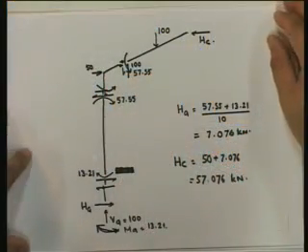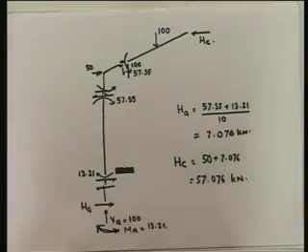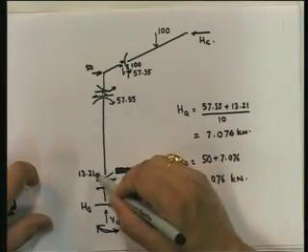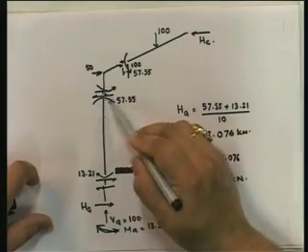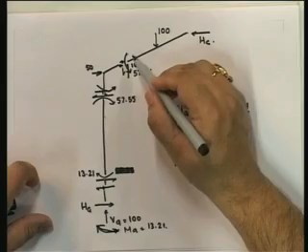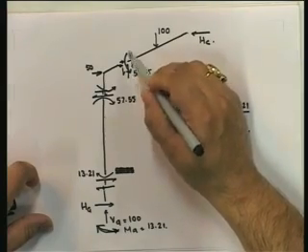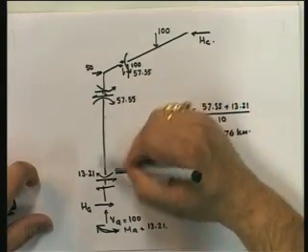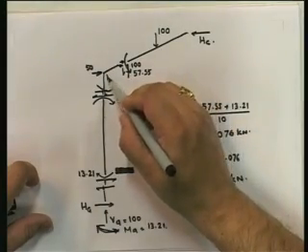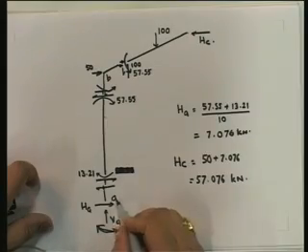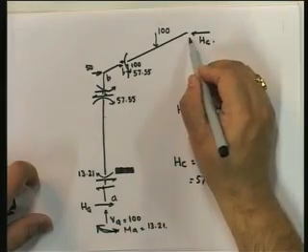So we've got the member end moments. In this particular case, the member end moment here is 13.21, minus 13 is clockwise, minus 57.5 is clockwise, plus 57 is anti-clockwise, and so these are the member end moments. Now this is the joint B, this is the joint at A, and this is the joint at C.